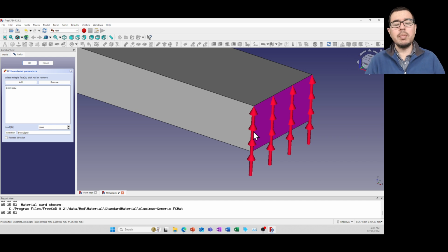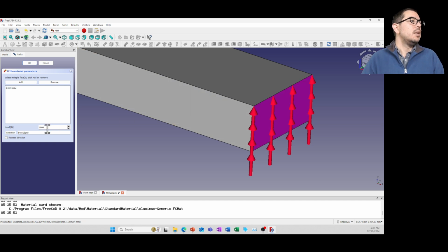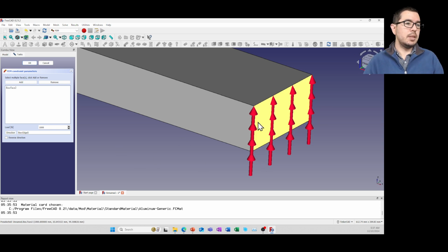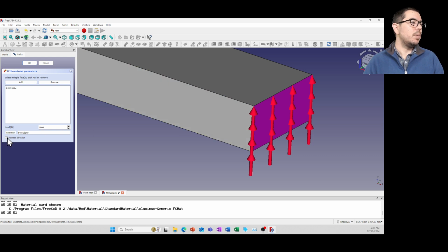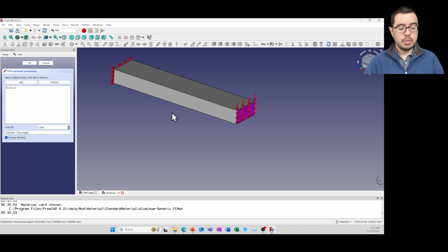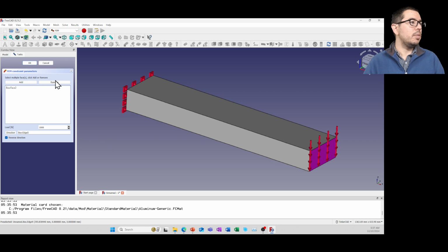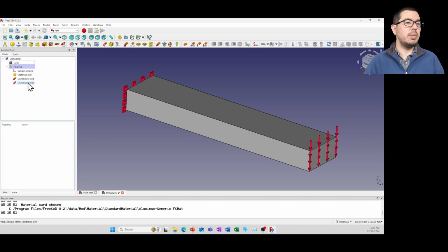It would be a symmetric problem and allow us to have a positive instead of a negative value for the z direction. I don't know if you can see the coordinate system, but the z is up, at least in the same direction as these arrows currently are. But let's go ahead and reverse the direction just so it looks a little bit more like what we've drawn on that table. So now we hit OK, and we've applied our constraints.